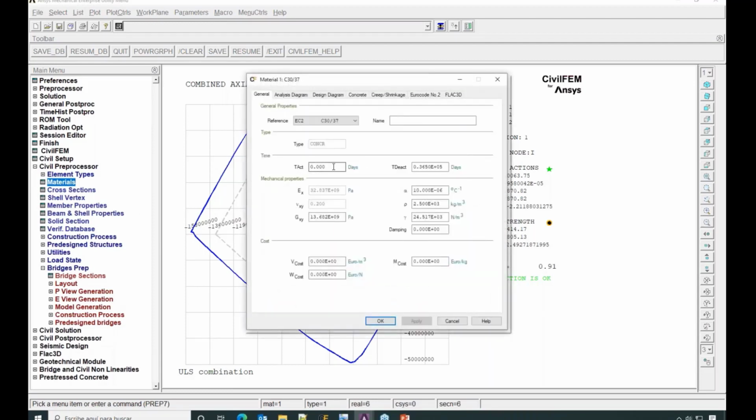For example, just for the calendar, you create a calendar time where you place a different concrete on the different parts of the arc. So you create different materials with different activation time. For example, you place concrete on day 0 in the first part of the arc. The next part is day 21, next, and so on. So you create different concretes with different activation and deactivations.